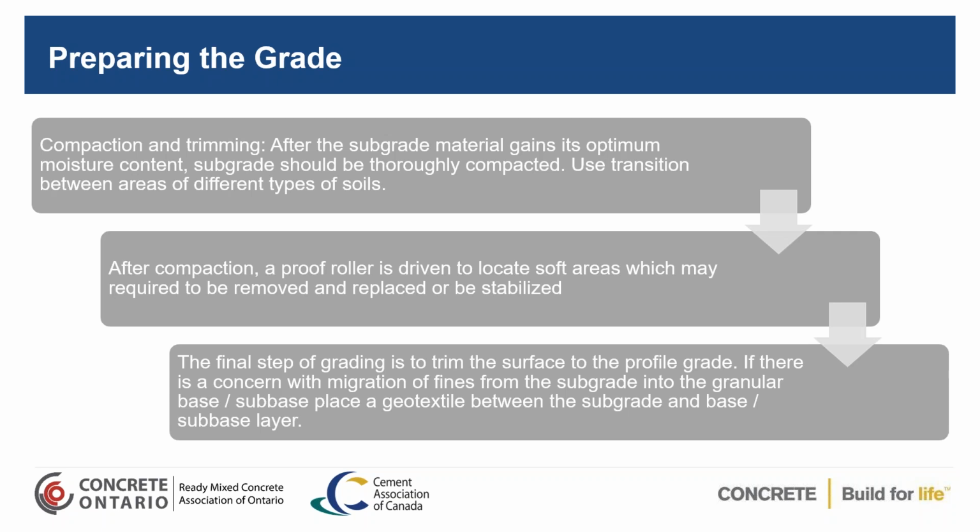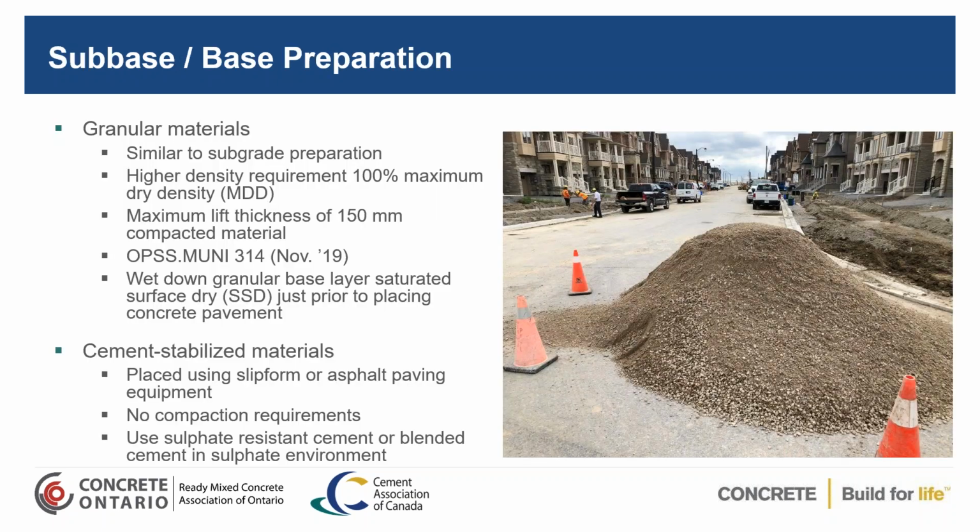pavement structure underneath it. So it's critical to have an engineering firm go in and do a detailed evaluation of what your subgrade material is, the types, the moisture contents, the densities, and determine whether you have a water table that's going to allow that migration of the fines so that you'll have a good performing subgrade.